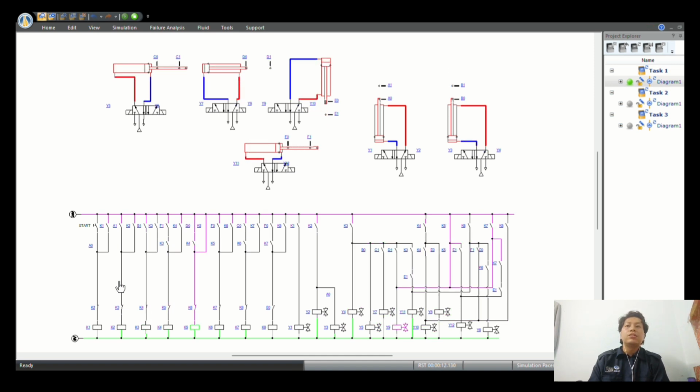When limit switch D0 and the relay K4 are active, the solenoid Y9 advances the cylinder E to E1, triggering the solenoid Y12 to retract the cylinder F. Limit switch F0 and the relay K5 will advance the cylinder F before solenoid Y10 retracts cylinder E.